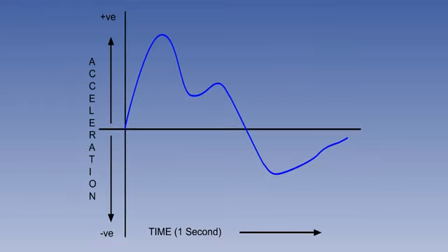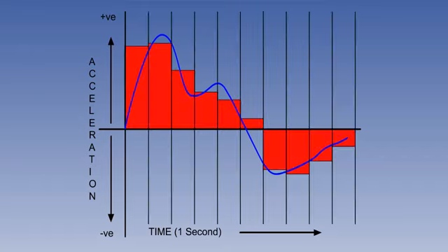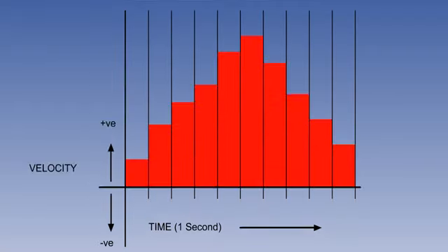Suppose that over a second the output from the accelerometer is an analog voltage like this. The integrator digital sampler will turn it into this. The input of acceleration, for example, is sampled many times per second, and each instantaneous value is multiplied by the time interval between samples. Adding all of these multiplied values together gives the total increase in speed over 1 second. Integration is a process of successive minute additions to, or subtractions from, the last known value to create a new value, in very small increments, but very frequently.